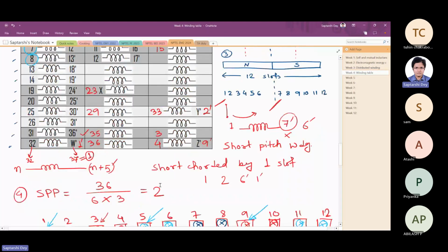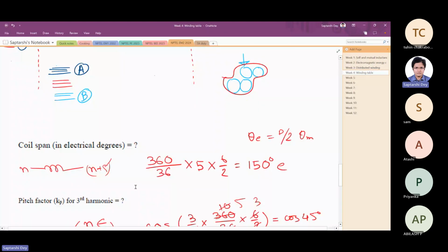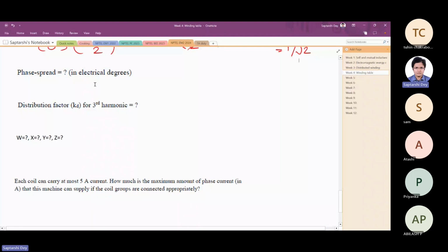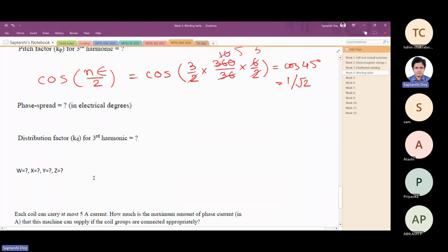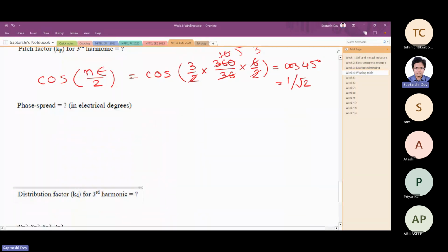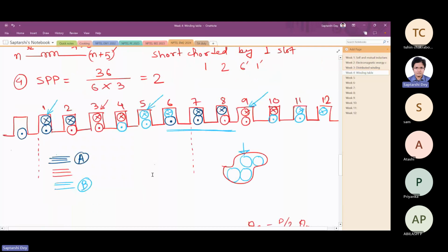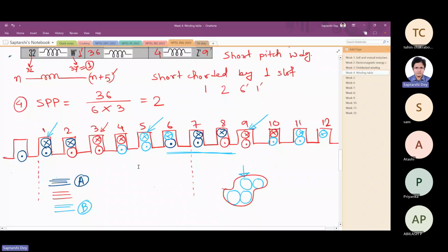It has to be under one pole, because otherwise it will keep changing from machine to machine, with the number of poles, even for the same winding distribution. Can you understand that keeping the same winding distribution, you can keep on multiplying this distribution to have more and more poles?